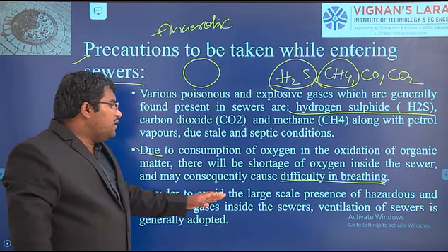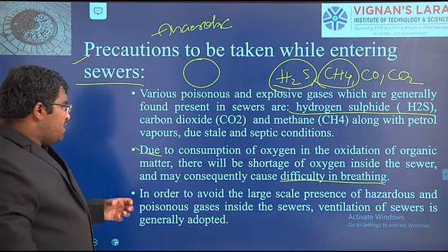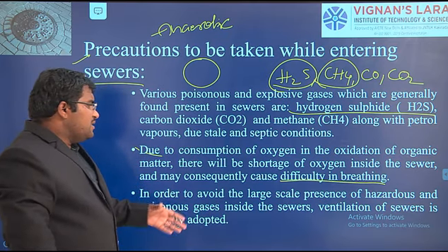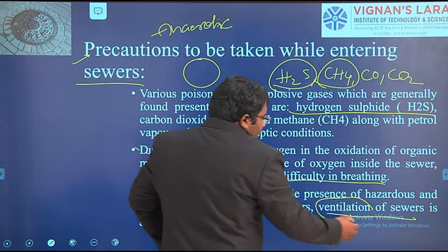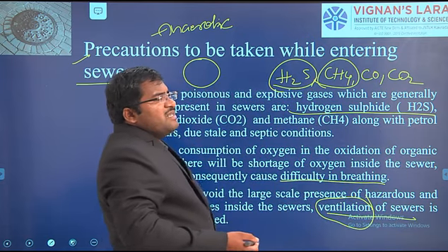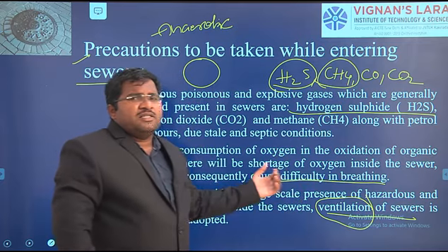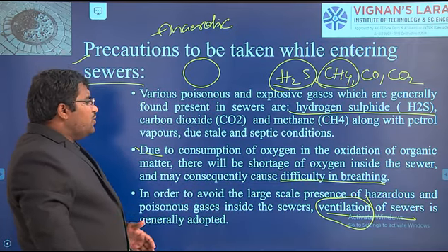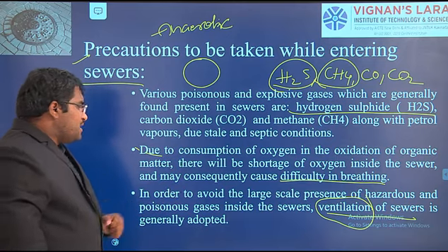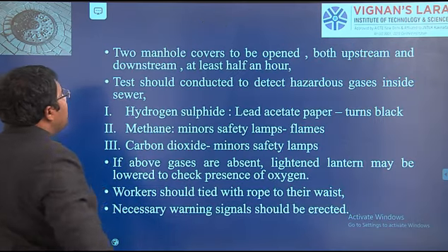In order to avoid the large scale presence of hazardous and poisonous gases inside the sewers, ventilation of sewers is provided to give more oxygen as well as to take out all these poisonous gases. So we have to do the ventilation process.